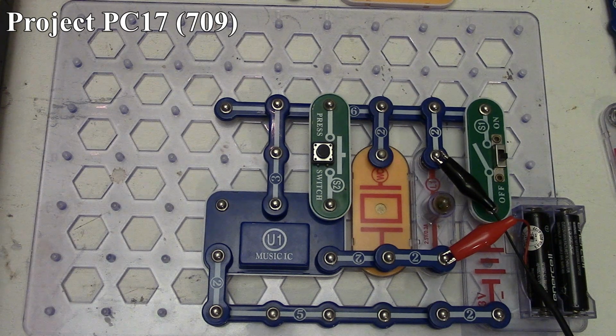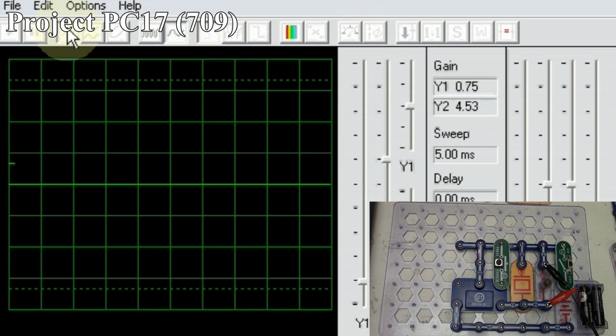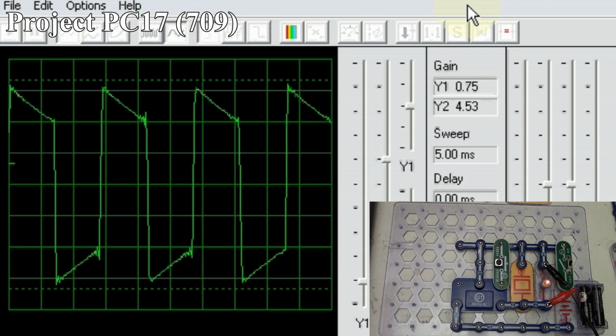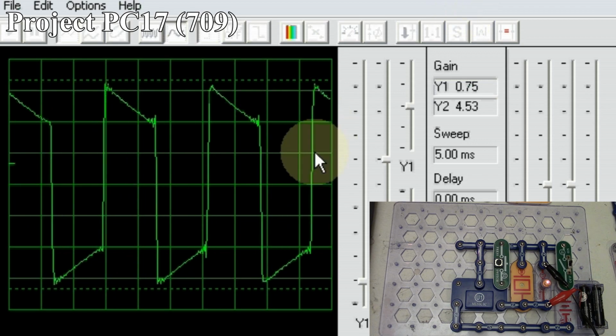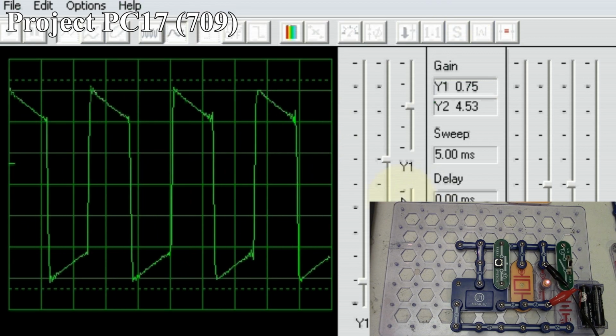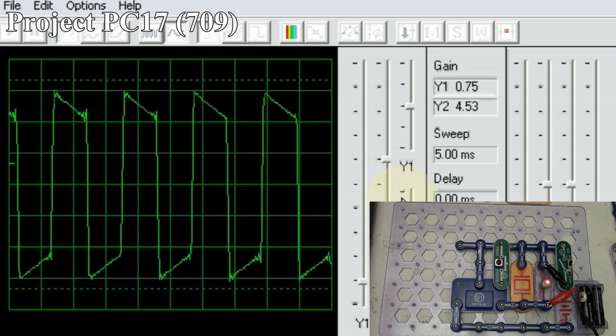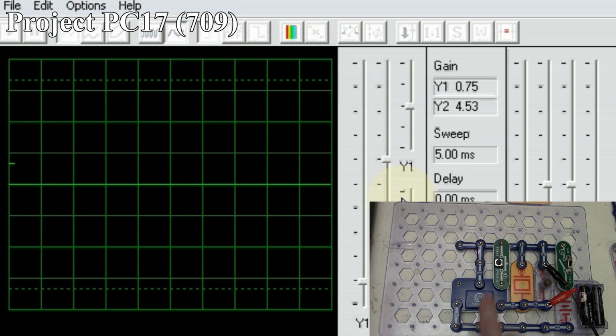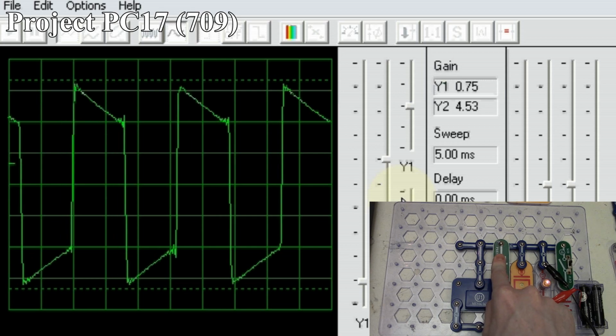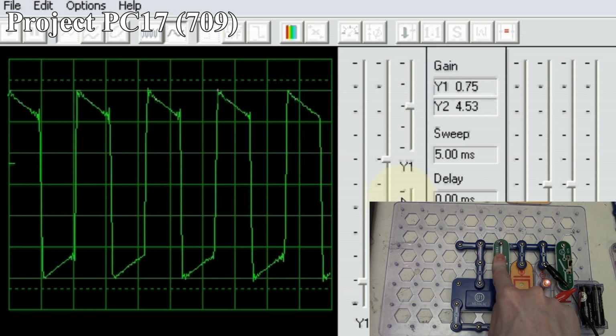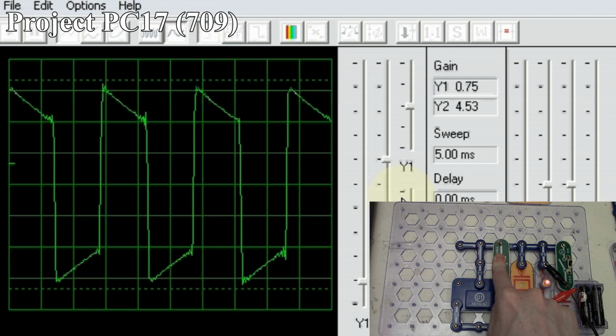So let me get the oscilloscope going. And we've got it already set up for a 0.5 millisecond division on there with some settings, so when I turn on the circuit, we can see this little sort of sawtooth type of waveform there. This thing goes away, and then of course I can bring it back just by holding down a press switch to keep it going.